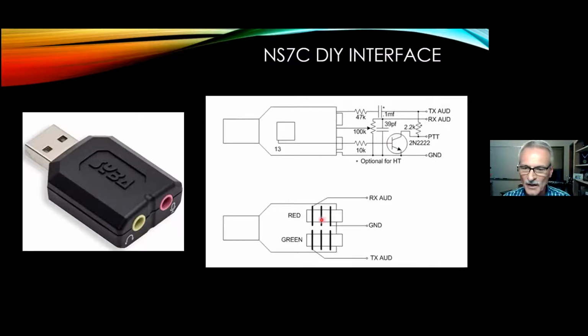It's got those two big connectors on there, and I don't even take those connectors off. The first couple times I messed around with one of these, I tried taking the connectors off, and even with my hot air soldering station, I loosened up the land traces on the board here. So just leave the connectors on. It's not even worth taking them off.